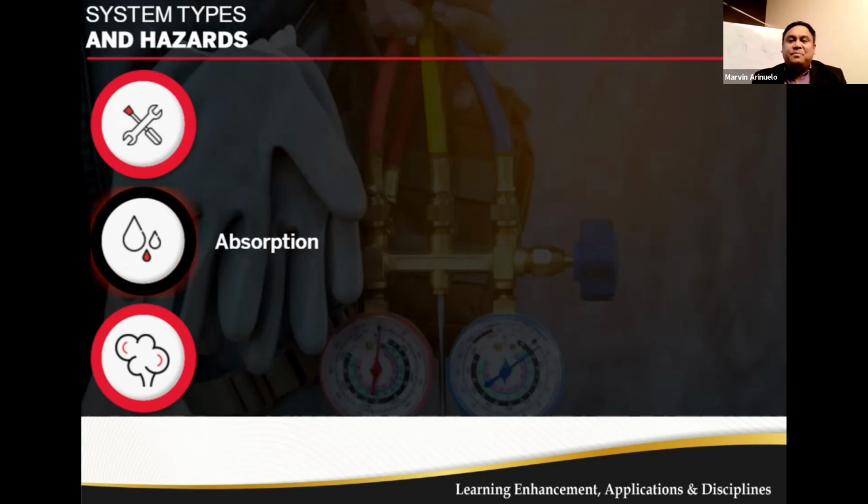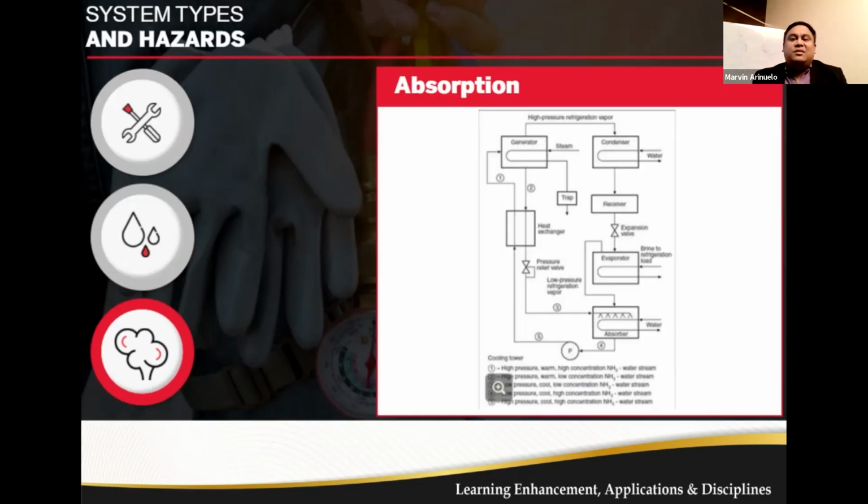The absorption system is mechanically the simplest, in common use today, and the oldest known for producing a refrigeration effect. This type of system contains basic refrigeration components: an absorber, heat exchanger, and generator serving as the compression step. The absorption cycle uses an absorbent as a secondary fluid to absorb the primary fluid, which is the gaseous refrigerant that has been vaporized in the evaporator. The evaporation process absorbs heat, which provides refrigeration. The two most common fluids are water-lithium bromide and ammonia-water. Water-lithium bromide is used primarily for air conditioning applications, and ammonia is used for large tonnage industrial applications.